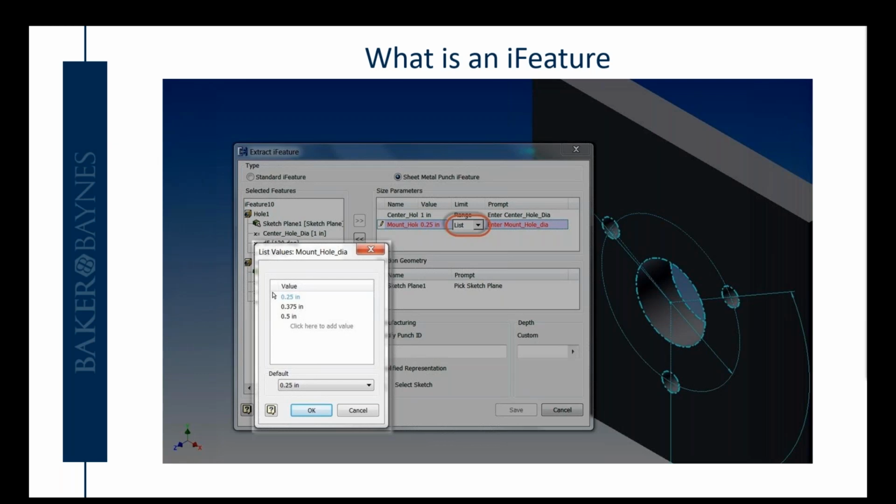You can create an iFeature from an iPart or from a set of features that is useful for other designs. iFeatures are created from existing features or sketches. To make it easier to create the iFeature, we use parameters that have descriptive names and apply those parameters to items in the sketches and features that will become your iFeature. Creating an iFeature with default parameters, such as D0, can be confusing to identify.